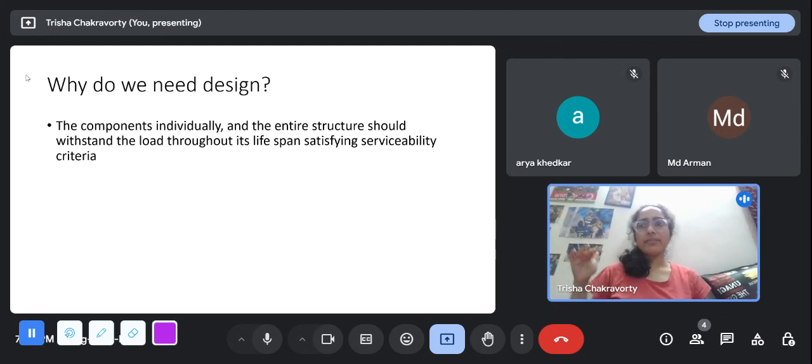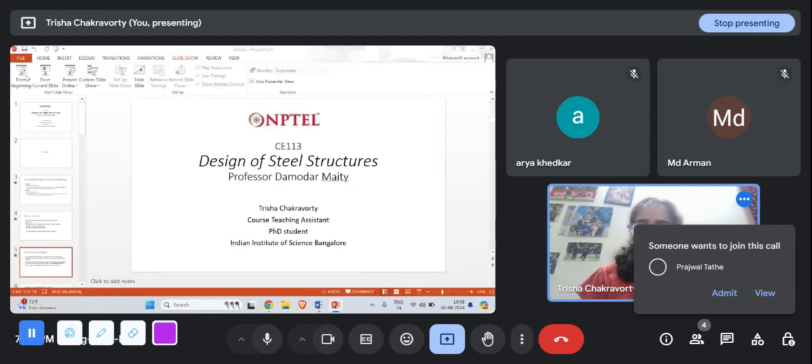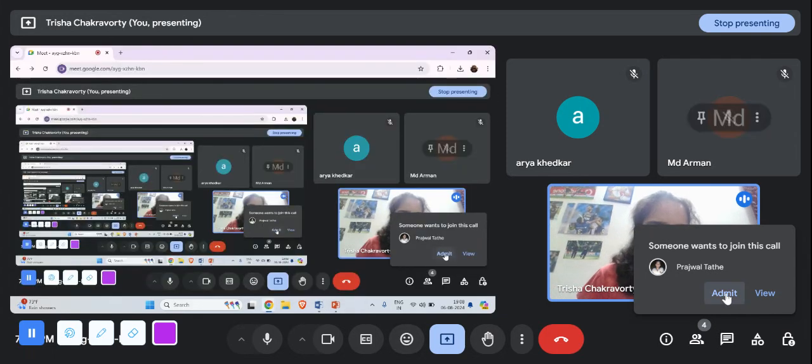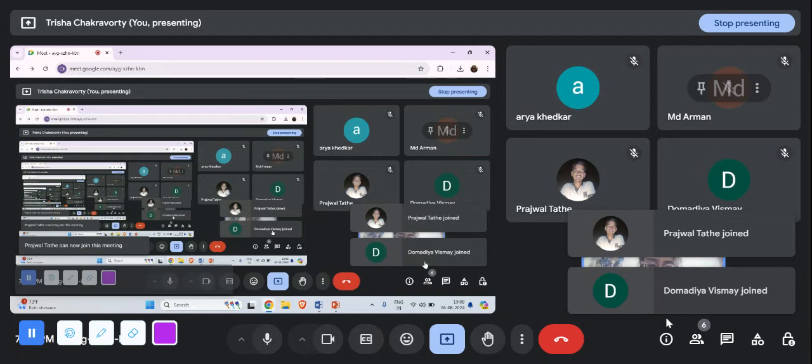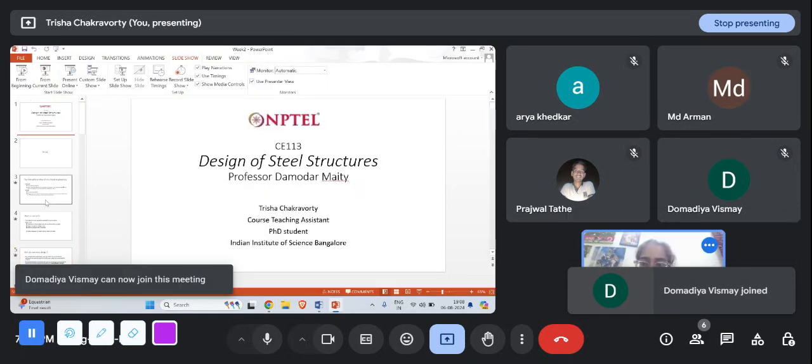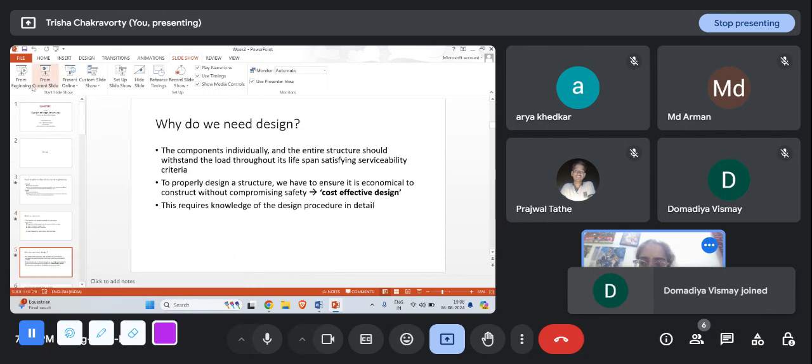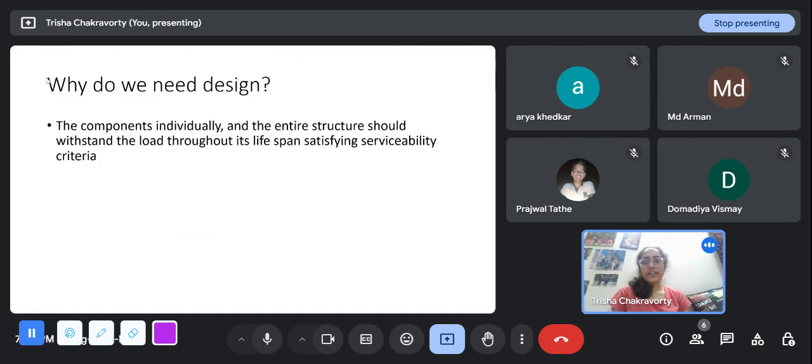The live load is everything else, every other vertical force that we are going to put on the structure, like the load of furniture. Sometimes furniture is confused to be dead load because it is an inanimate object, but furniture is also live load. Only the self weight of the structure and the floor finish is a dead load. The live load is all other vertical loads that we are going to apply on the floors: the furniture, people, or whatever. And in the case of bridges, the vehicle loads are live loads, and wind load and earthquake load are lateral loads.